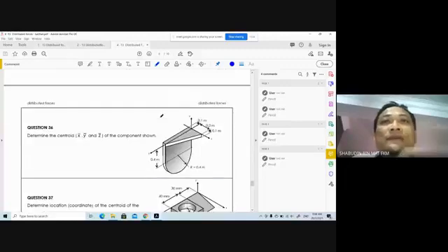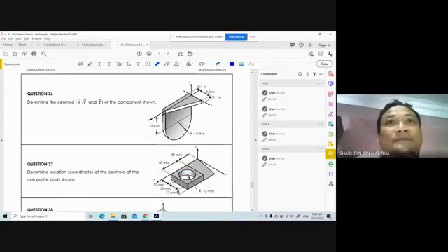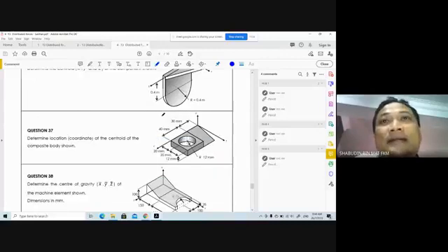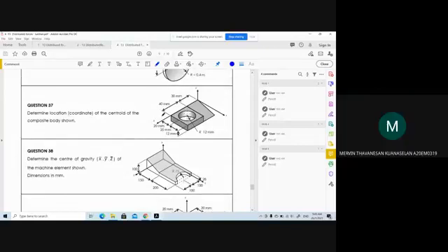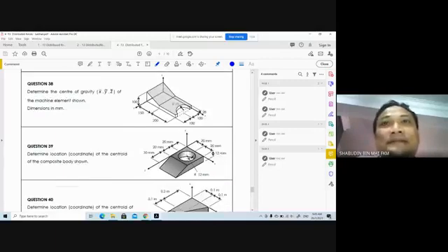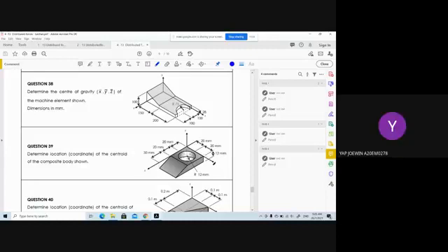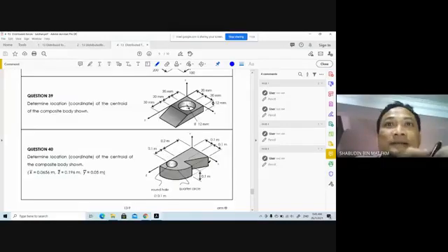There we go to this question. Is it symmetrical to any axis here? No. That one, is it symmetrical to any axis here? Z. Z bar again, Z bar is 100. Any symmetrical to any axis here? That one. X. X bar is equal to 20. And that one?